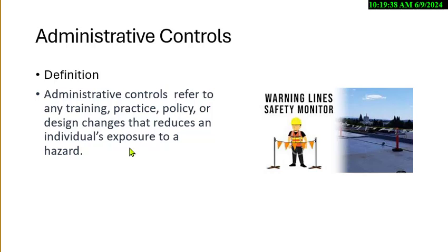When I started in OSHA, back in the early days, I thought this was crazy because you would have to actually watch the worker fall if you were doing it right. But what we found out is that it's a heightened sense of awareness if the monitor is watching. It's very expensive to pay somebody to do nothing but watch, so it's a lot easier to put portable guardrails up now than it is to do this monitor system. But that is a control. Statistically, it does lower the injury rates for companies that do use it.